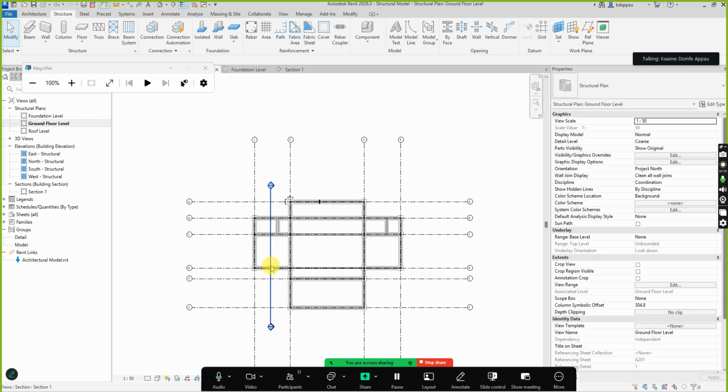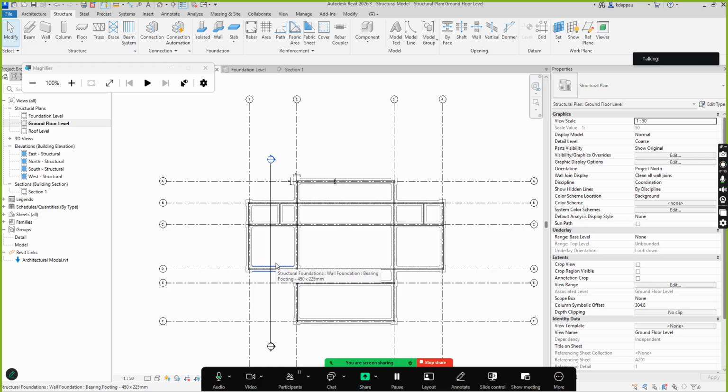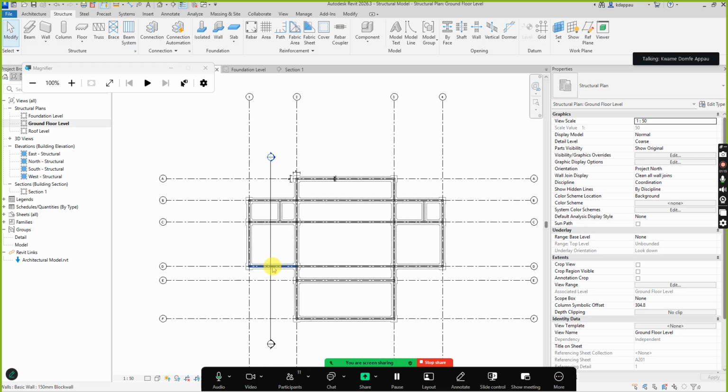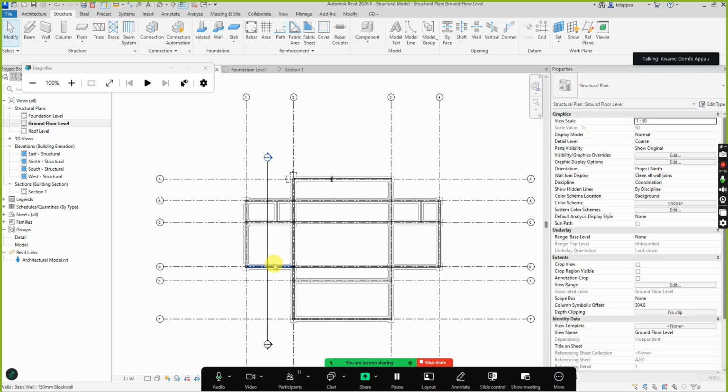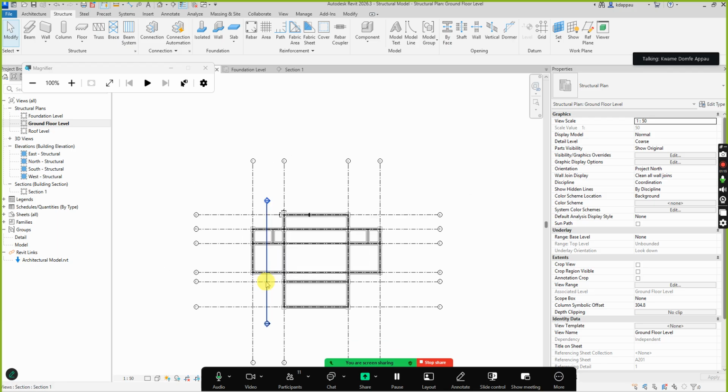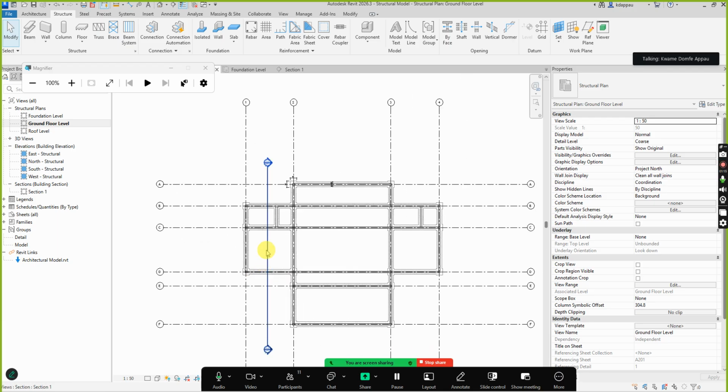So, knowing how to model is one thing. But being able to model for it to mimic real world situations and solve real world problems requires another understanding, which is not just about Revit modeling, but it's about engineering, yes. It's about architecture, it's about construction, it's about services, it's about everything. For instance, exactly, you are going to do servicing. If you don't know that waste pipe is supposed to be, say, 4 inches, or a water supply pipe is supposed to be, say, 1 inch, if you don't understand those principles, you will just pick any pipe size and